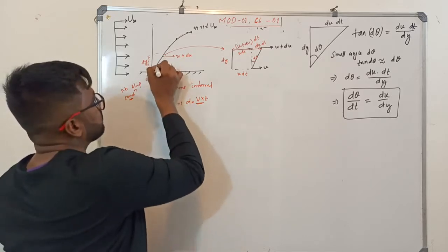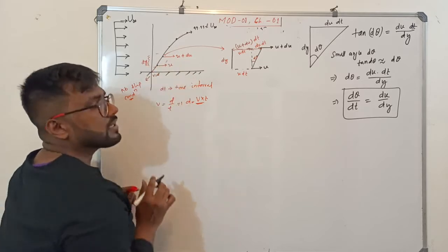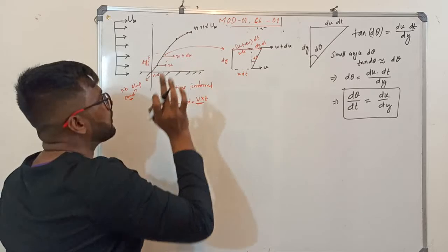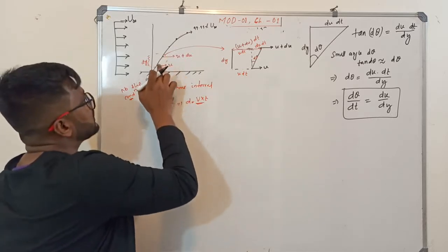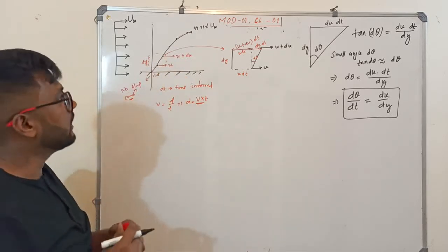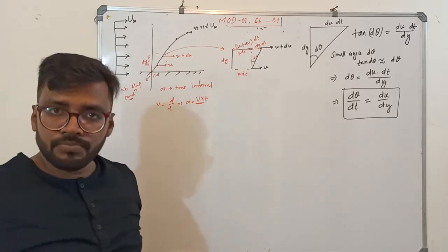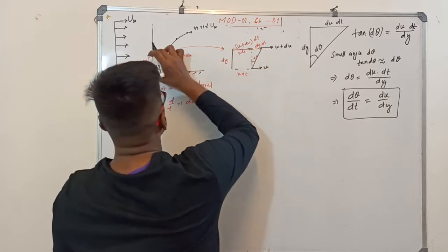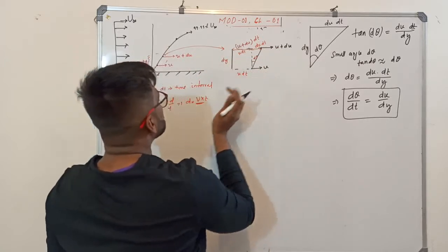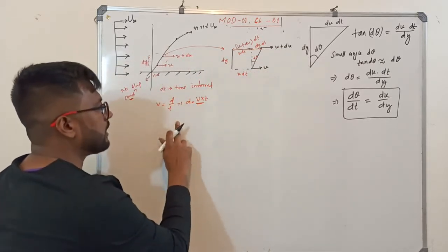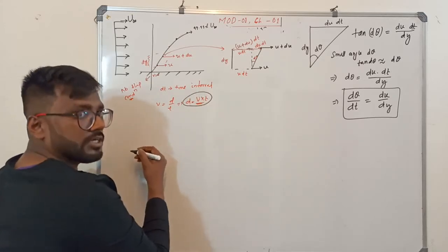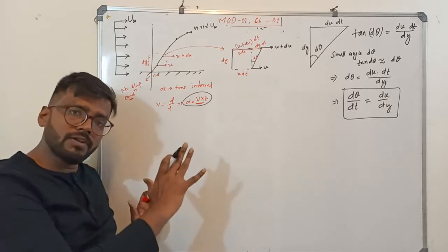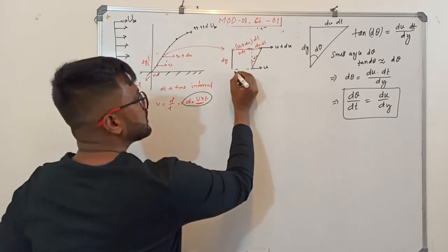Then we took the first particle, where the velocity is u. We went to the next particle. Obviously its velocity is more than the previous one, it is u plus du. Let us say these are at a depth of dy. This is what I have drawn here. This is your particle, and this is the other particle. What will be this distance? Velocity equals displacement by time, and displacement equals velocity into time. Displacement equals your velocity into time. So this is your u dt.